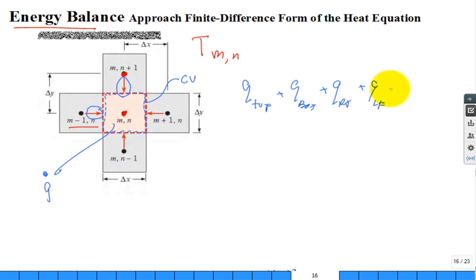I can have even some Q source, because all of these, the way they're shown, which is the direction of the arrow? It's bookkeeping, and it simplifies it and helps you avoid plus minus errors if you just say everything's into the node of interest, into the control volume of interest. Hence, the source would be a plus in front of it. Now, if it's steady state 2D, boom, that's it.